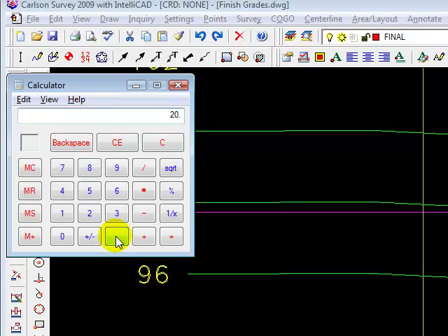So if we have a 10-foot change horizontally, we can expect to have a 2-foot change in vertical elevation. So that's the process that I go through. The numbers that we're using here are nice and easy. You could do the math in your head, but if you had an odd site with some odd spacing in your contours, this is the process that you would use.